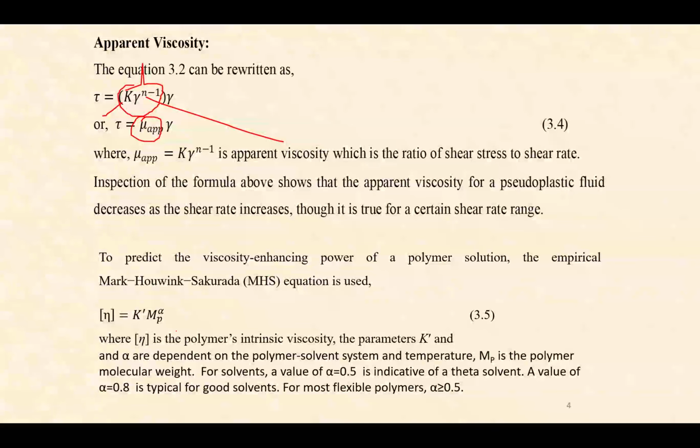And there is another parameter, particularly when we are talking about shale gas, shale oil or tight reservoirs. If we compare it with a conventional oil and gas reservoir, where the permeability or porosity is significantly high compared to the shale or tight reservoir, then the molecular weight of the polymer plays a very important role. This molecular weight is related to the viscosity.